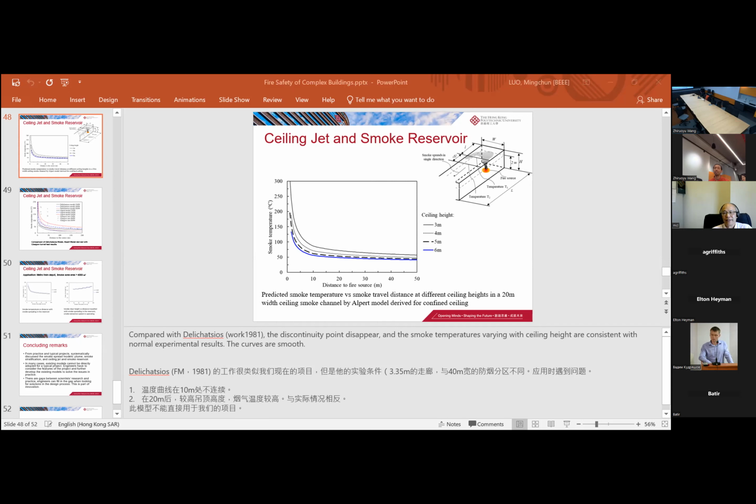the fan capacity. But for fire engineering design or performance-based design, we can start from the design fire size, the heat release rate, and use the plume model to tell the engineer what smoke extraction rate is needed. And then for further detailed study, you can use FDS, CFD models, and other tools to do the assessment.